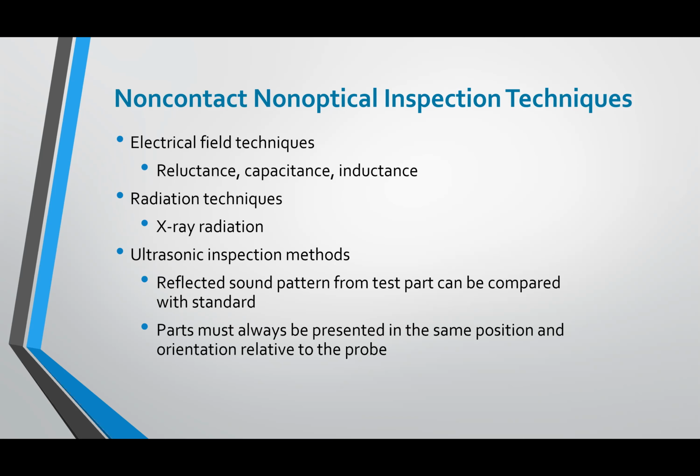So for example, if you have a multimeter, those measurements can be done. X-ray techniques can be done. Again, that also might be used for welding, as some welds are X-rayed depending on the criticality and where they're located. And then ultrasonic inspection is using sound waves. That can be used for thickness or also position and orientation.